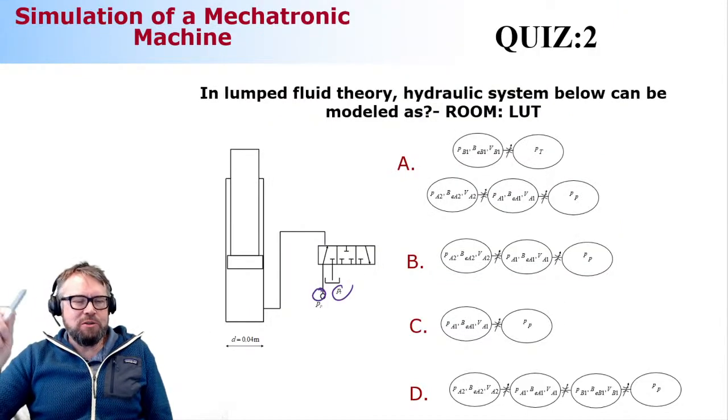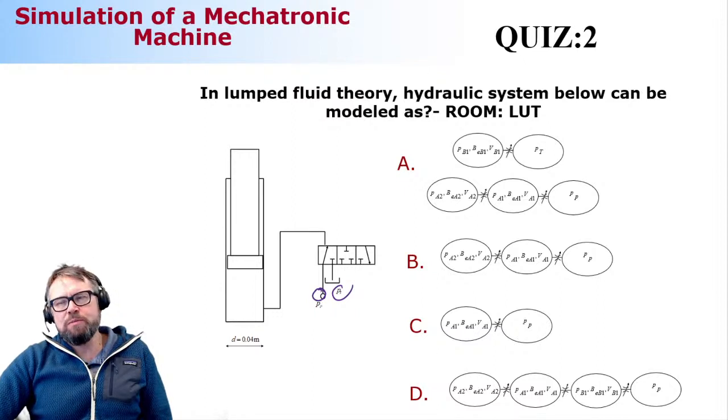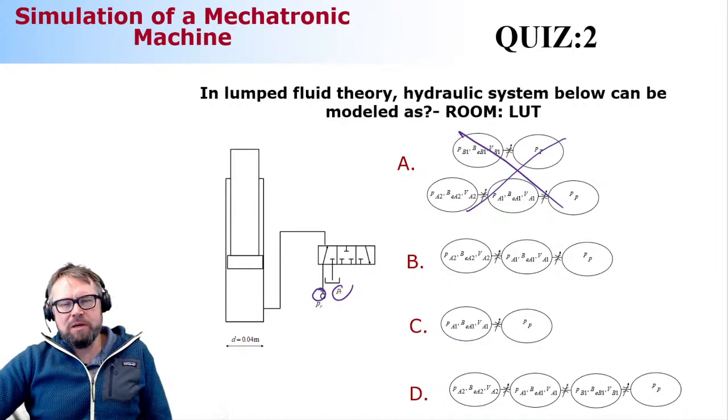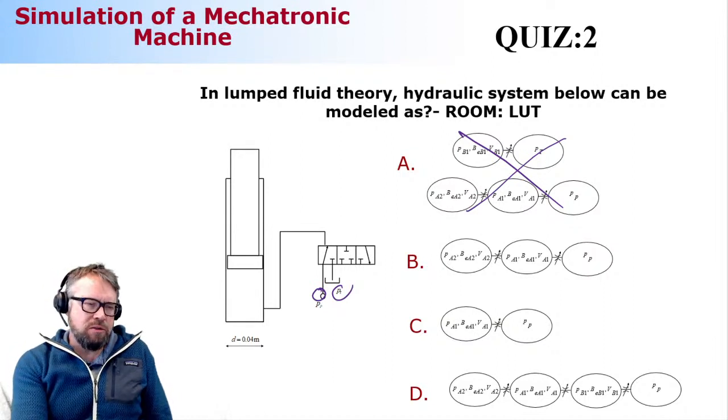All right. So the first thing to do here is that we need to understand that this is a one way cylinder. The cylinder is operating only in one direction, so there is no pressure on the piston rod side. So all these components that have two different channels, which is this one here, just one, is off the picture. This cannot be the correct one. Then you need to also understand that this hose line is connected to this hydraulic cylinder.